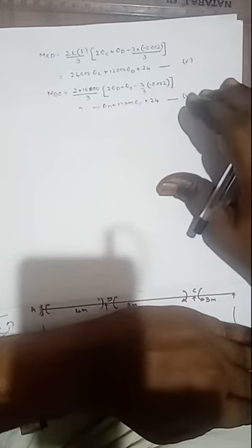Then similarly we can write one more equation from the opposite end, that is from D, that is from the last support, that is 2 into EI 18,000 divided by L, that is 3 inside of the bracket. Here we are writing from the end D, hence that is 2 theta D, that is 2 times near end slope, plus 1 times far end slope, that is theta C, minus 3 delta. 3 delta is minus 0.002 divided by L, that is 3 meter. Then this one becomes 24,000 theta D plus 12,000 theta C plus 24. This one is equation number 6. Here we have written 6 equations, 2 for each span: for AB 2, for BC 2, for CD 2 equations.